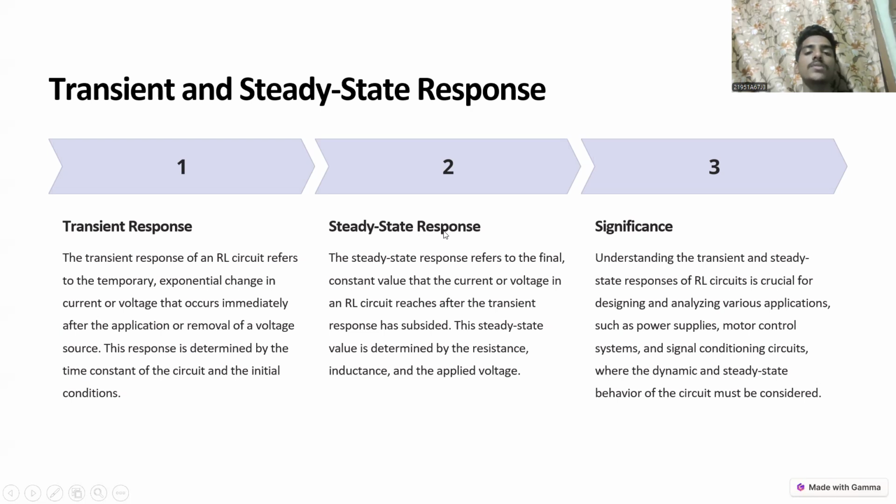Steady state response. The steady state response refers to the final constant value that the current or voltage in an RL circuit reaches after the transient response has subsided. The steady state value is determined by the resistance, inductance, and the applied voltage.